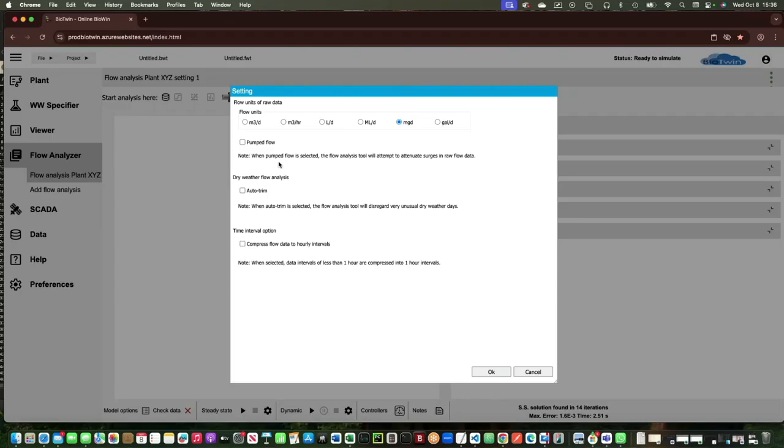You know, let's say you see no typical diurnal trend in the raw data, then what you could do is check this box to identify it as being pump data from, say, a wet well, and that just makes it more likely for you to discern a diurnal pattern from that data set. So there's some smarts built into the API to take care of those scenarios. For now, this isn't a pump data set, I don't think. I mean, we'll see.